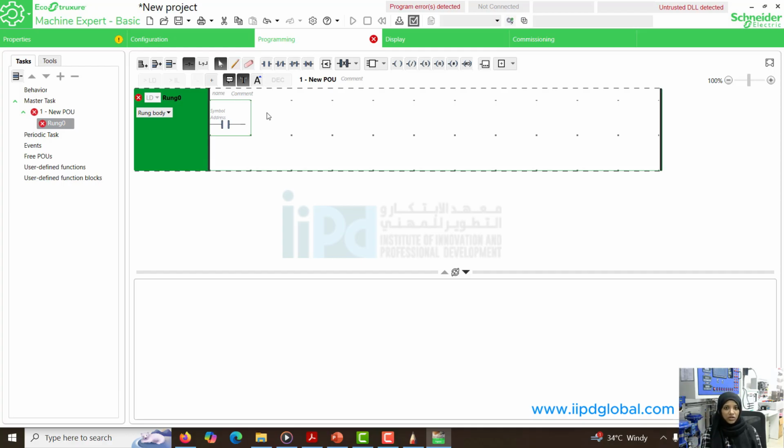Now we also have the down counter, where you start with a full packet of items and want to release the items one by one. Or you have a car parking area with 50 cars inside, and one by one the cars are going outside and you want to know the count. In that case you set the value as 50, and one by one when a car goes out the value decreases like 49, 48, etc. Once it reaches 0, that is the done of your down counter. In industry, we have applications related to up counter and down counter.